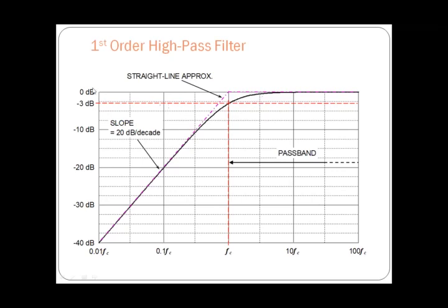You can see the maximum gain is at 0 dB, as this high pass filter is made up of all passive components. The gain will not be improved by these passive components, so the output is equal to the input. So we obtain the gain as 0 dB at the highest frequencies.